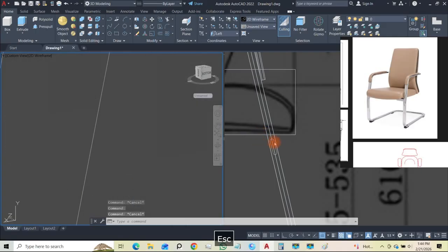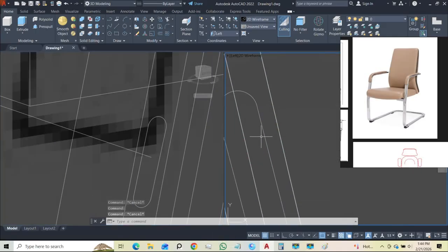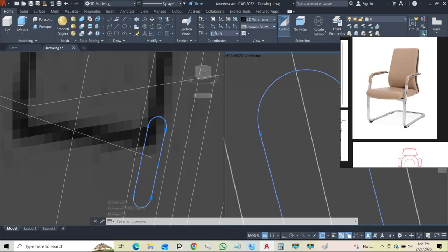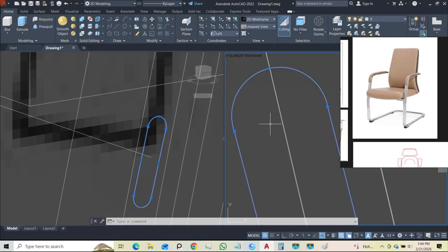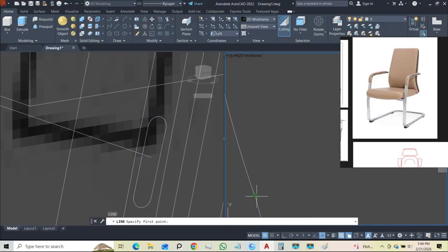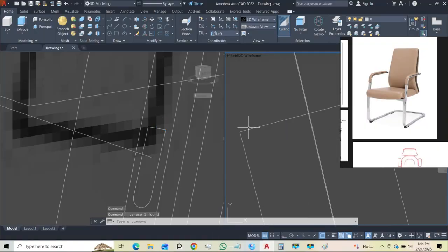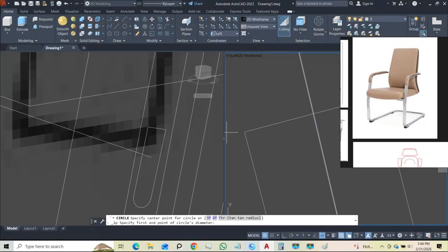So what I will do is I will come back here, check the mesh out. If it's not joined, I get that. I knew that. So there's something wrong with that. So what we can do is draw a line from this point all the way to this point. X to explode this so that we can remove this segment. And then let's run this again.